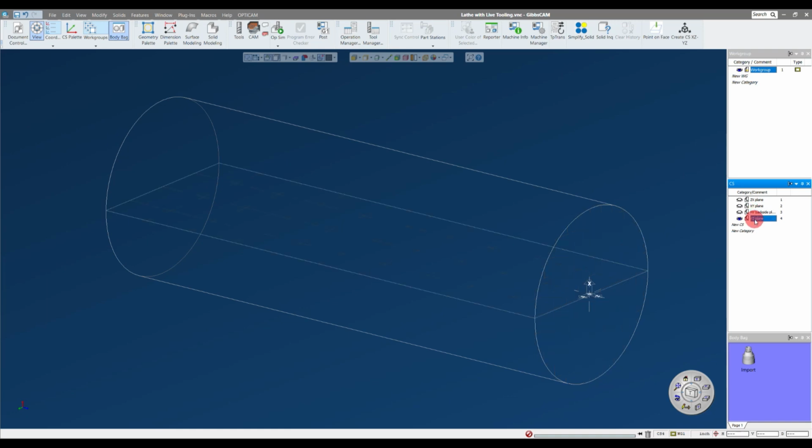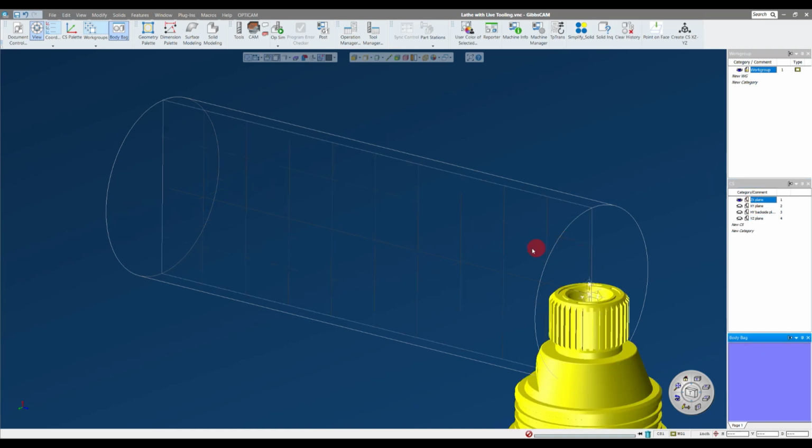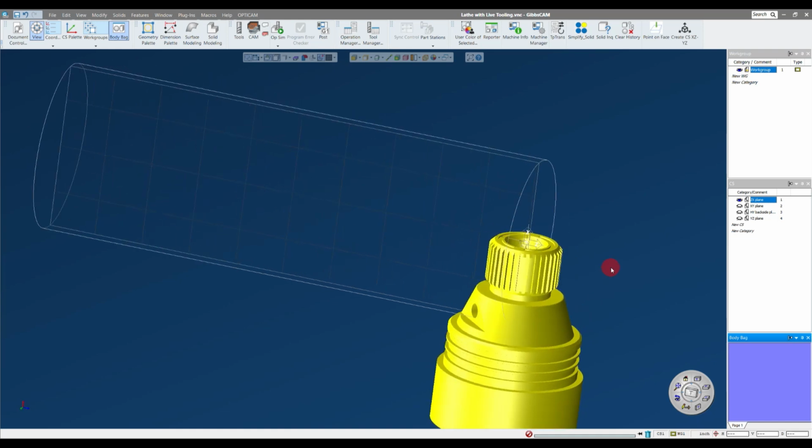And the YZ coordinate system, and this is in general what we're going to be using for any radial milling operations on the periphery or the diameter of the part. And again, we're going to be taking a much deeper dive into these coordinate systems a little bit later. So in general, most of the time you'll have all the coordinate systems that you'll need for most parts, but it's very easy to create, manipulate, and modify coordinate systems should you need to create more depending on the parts that you're machining. So I'm going to bring my model back out, and I need to get this thing oriented.